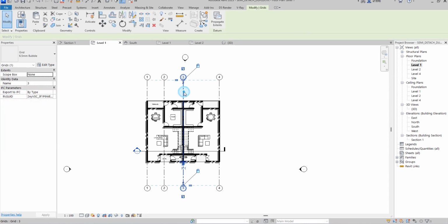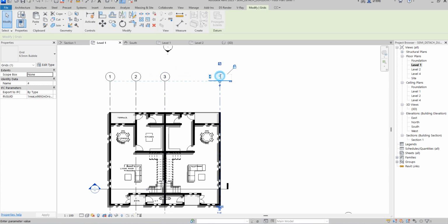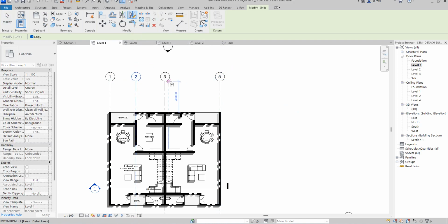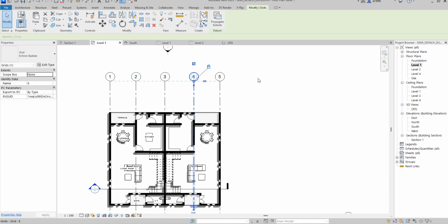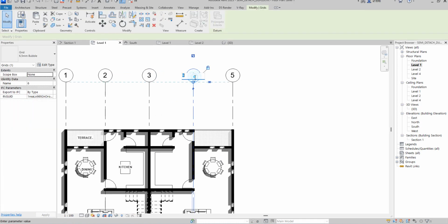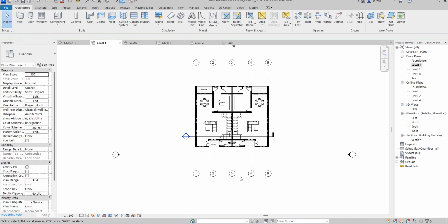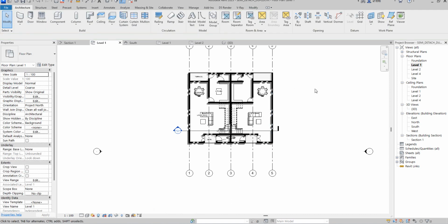Whatsoever we want to be doing here now, we have grid lines as our references. This is the middle grid line which is working. So like this one now, you can change this one to 5, then you select this one and mirror it to change to 6, but you return it back to 4. So change it back to 4. That is grid line 4. So you have this grid line across all the areas where you're having it. So the horizontal grid line, we do that later.